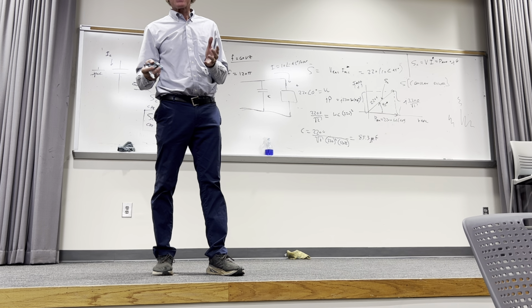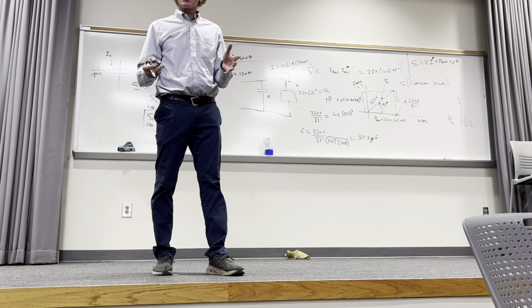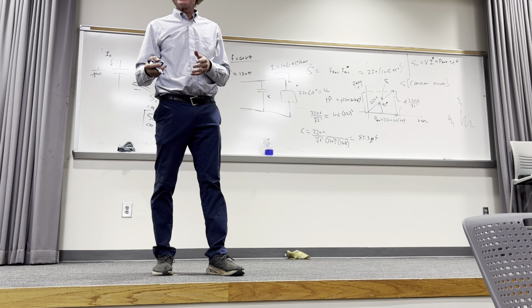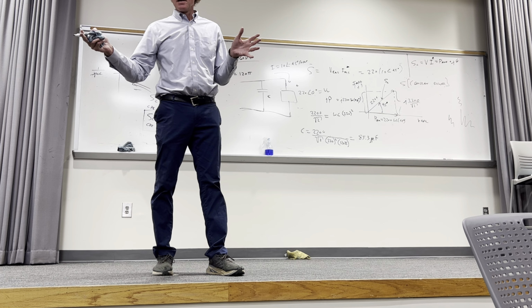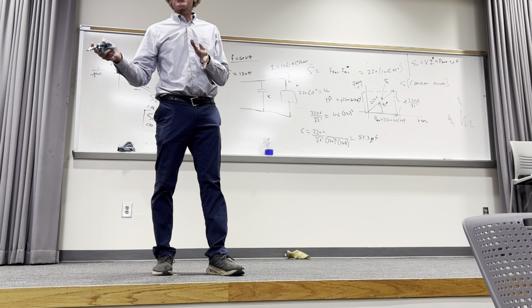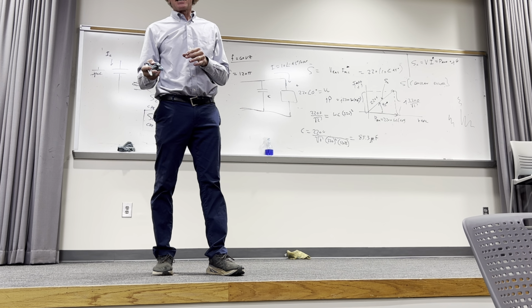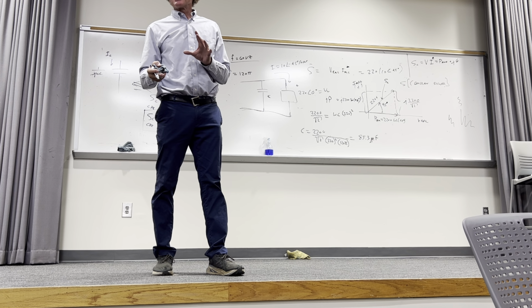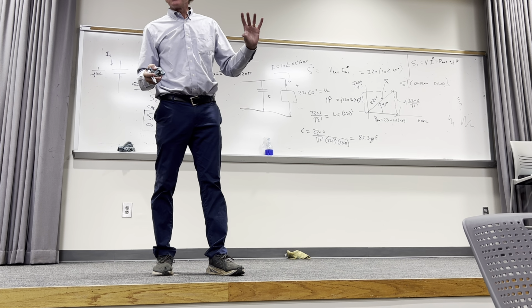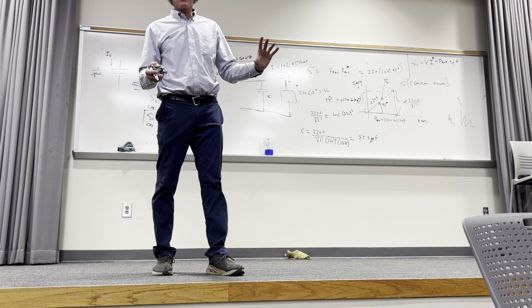So this is a practical thing if you ever work out there. Some of you in industry, when you're dealing with energy scavenging technologies, now MEs are probably the people I'm speaking to, you're going to be dealing with a whole lot of that in the future. And if you're going to be in any kind of cutting edge car development, the brakes, everything are energy scavenging. Make sure you don't forget to design things, if it says it can stand 220 volts and your estimate of the worst possible case is 200 volts, so oh, it's okay.